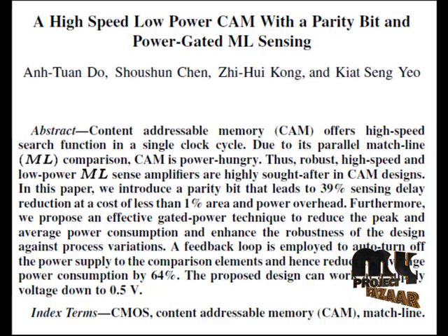A memory that is accessed in this way is called content addressable memory, or CAM. To achieve effective data searching, the data comparison architecture of CAM is usually implemented in a parallel operation structure. However, due to this parallel processing characteristic, power consumption is always an important concern while designing the CAM circuitry. That is, content addressable memories simultaneously compare an input word to all the contents of the memory and return the addresses of matching locations in a single clock cycle.